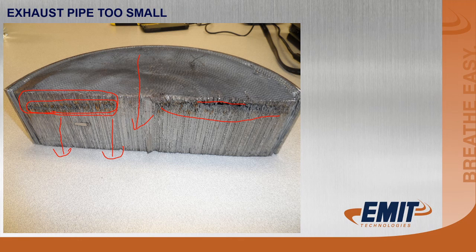It no longer is tumbling, and you've depleted the oxygen that's in the foil and also in the exhaust stream that can react, that's making contact with the sites, precious metal. So we know that in an NSCR catalyst, the activity is on the leading edge.